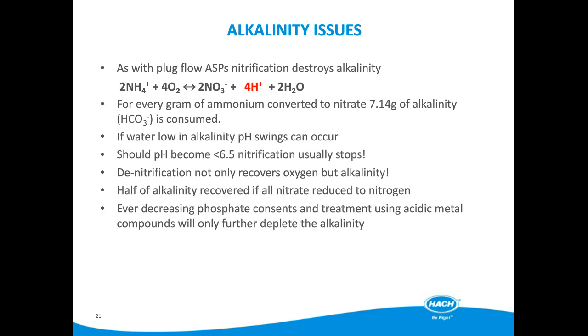Unless the process has become specifically acclimatized to operate at low pH, nitrification usually stops at a pH of less than around 6.5, making alkalinity and the control of pH a critical parameter, especially in soft water areas. By introducing ANOXIC conditions, either in the ditch itself or an external ANOXIC zone, half of this consumed alkalinity can be recovered, which can mean alkalinity dosing may not be required.